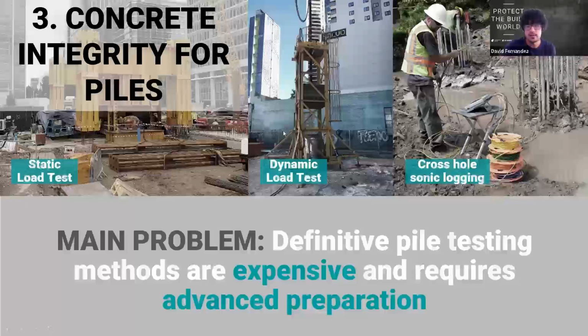And then this is similar to the dynamic load test. And lastly, we have the cross-hole sonic logging, which is a non-destructive technique, but it requires placing some embedded tubes inside of the pile prior to the casting of the pile. So you can just insert these cables with the sensors on it.